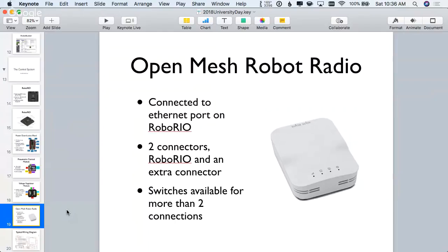So after you crimp connectors, yank on them. And when you put the screws into the battery, or you connect the wires to the battery or the wires to the power distribution board, make sure you can't move them, that they're really cinched down tight, and all that stuff.